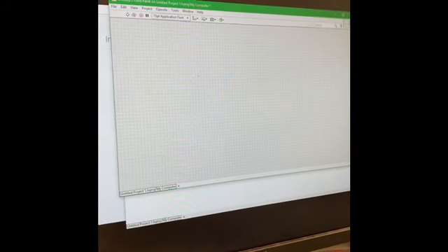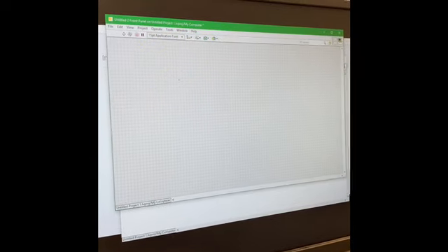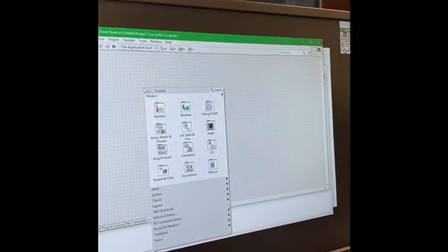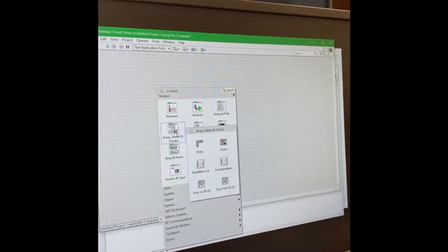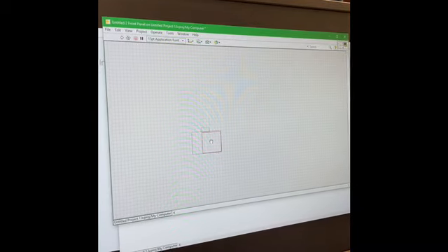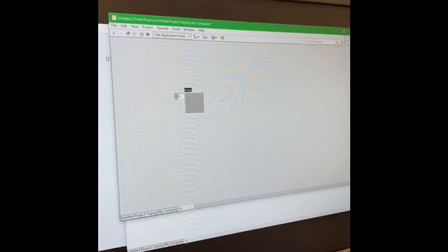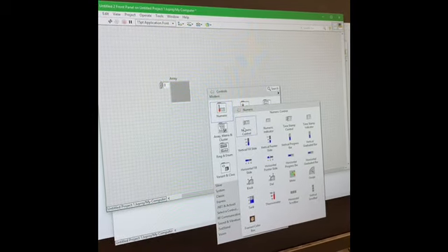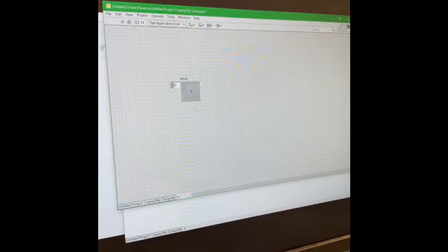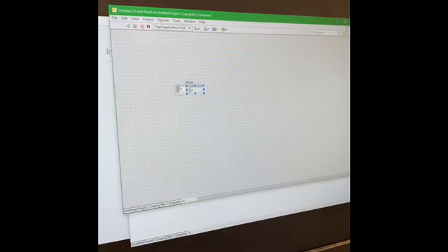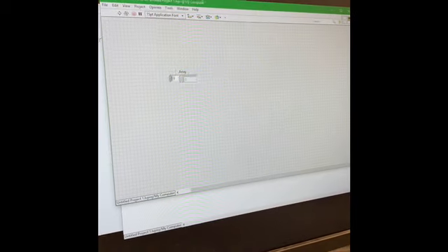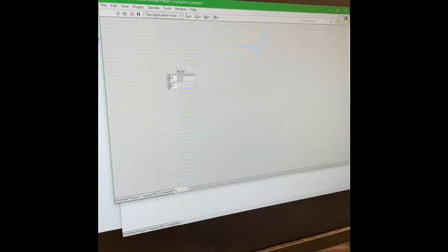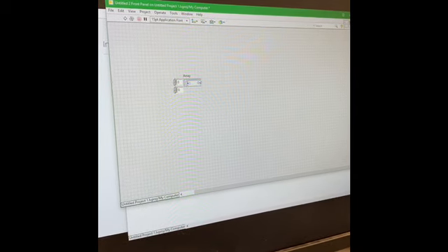Okay, so this is part 2 of Lab 3, and we're using LabVIEW to calculate the linear equations. First, we're on your front panel. You'll right-click, scroll to Array, Matrix and Cluster, and then over to Array. And you can place that on your front panel. You'll right-click again, scroll to Numeric, and to Numeric Control, and you'll place that in your array. Then you'll select your entire array, right click, and scroll down to add dimension. And then we're going to make it a 4x4 matrix.